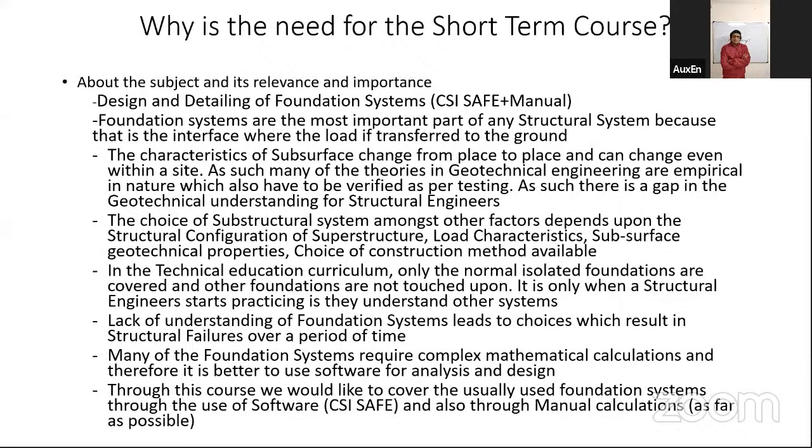Testing in itself becomes pretty expensive. Only in large sites will you find that the necessary number of tests are conducted. Otherwise, testing frequency, at least in India, is pretty low. So testing is low, and variations in subsurface profiles can be large.